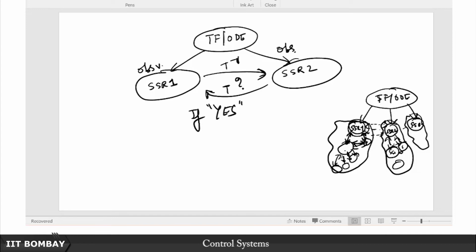We have already seen that in an earlier lecture, right? But that is really not a system theoretic property. It is just some choice of a matrix that we have made, some non-singular matrix. But now we have seen that since this property of observability is invariant to similarity transformation, it begs the question: is it true that if you and I independently get two observable realizations of the same transfer function, then they can always be related using a similarity transformation?